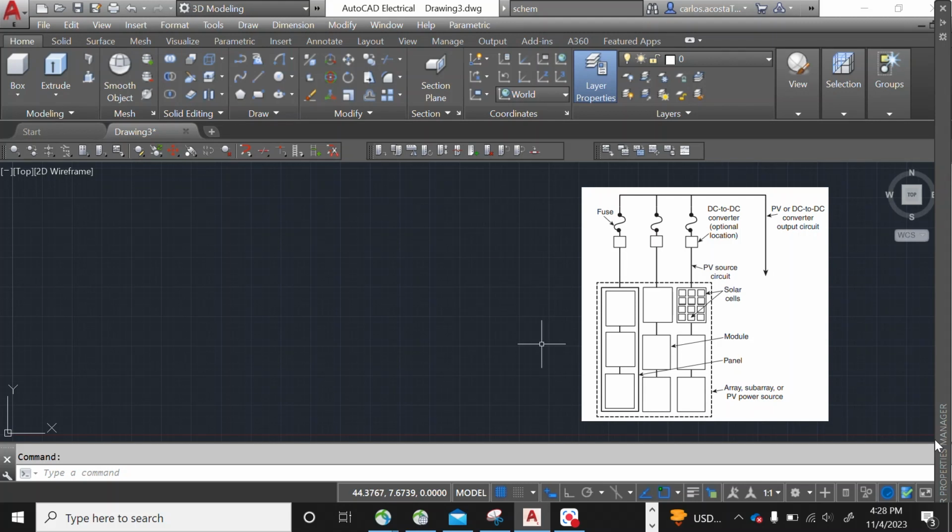Hello, let us look at wiring electrical panels or electrical connections. For this field of electrical connections, by following standards and norms, the most common drawings or wire diagrams are the one line diagram. When you have a single line diagram, your wires are represented by a single line, but they could be multiple lines in that conduit. For instance, if you have a three-phase power represented by a single line, in that line you're carrying three phases, phase one, phase two, phase three, obviously, plus ground, but your drawing will only have one line. And that is a very common representation of wiring diagrams because they're standardized by norms.